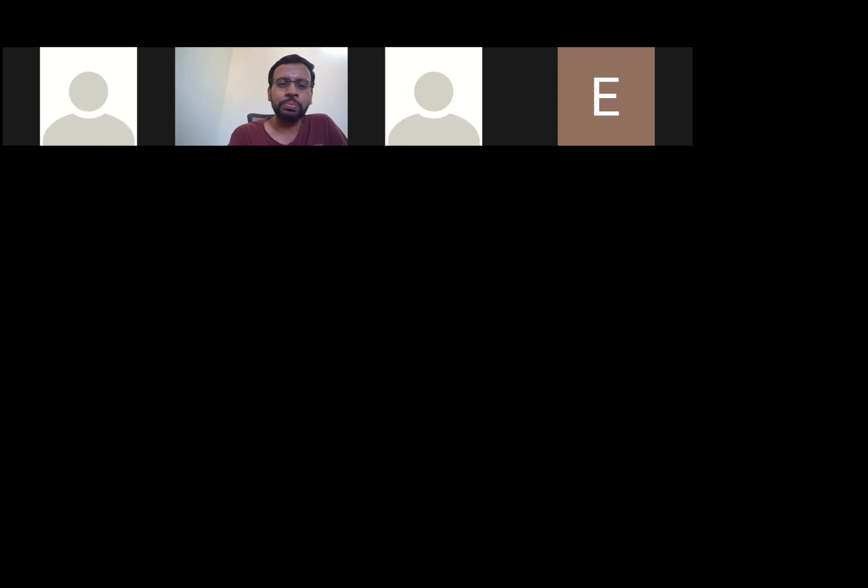After you do an operation which is somewhat equivalent to low pass filtering, a Gaussian smoothing, that's after all a low pass filtering, you could see the artifacts are essentially high frequency content in the image. The moment you low pass filter with the Gaussian before doing subsampling, you could see in the example I have shown in the video that you could get rid of the effect of artifacts or aliasing, right? And for the audio, that demonstration is, I think, good enough to get a clear picture of that.